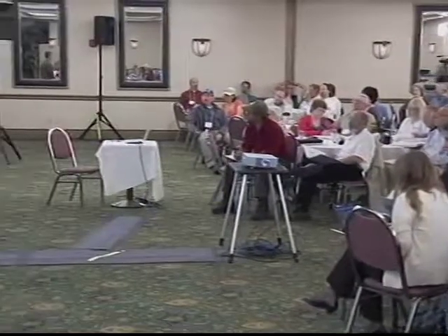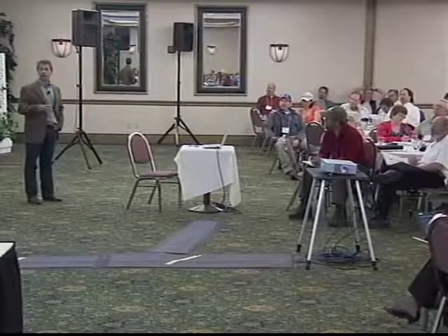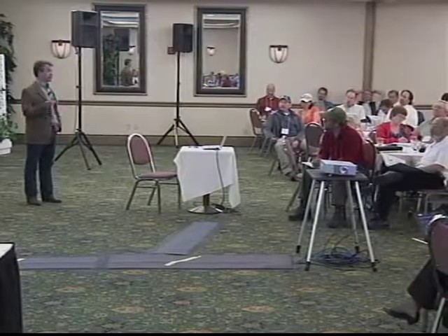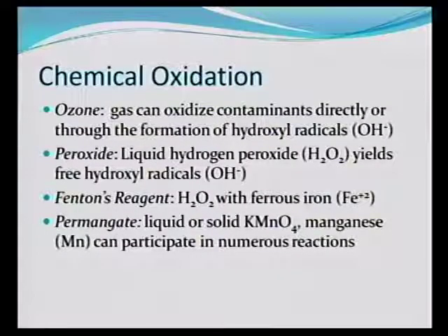a treatment process, and where's that going to go? Where's that water going to go? Where's the stuff you extract going to go? It's got to go in another landfill somewhere. So it'd be nice if you could treat it in place, and we don't have to worry about extracting it. So one way to do that is, rather than pull the water out and treat it, we inject reactants into the formation to try and degrade it in place.